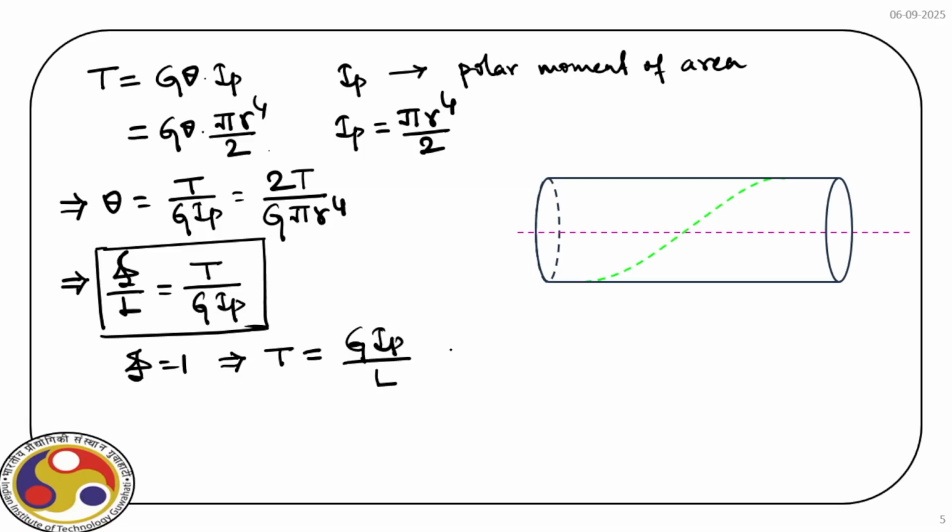And this is called torsional stiffness. Recall the definition of stiffness. It is the amount of force required for unit deformation, and in case of torsion, it is actually the amount of torque required, here you can see, for unit rotation, right, over the complete length.